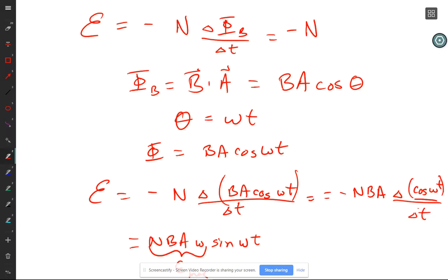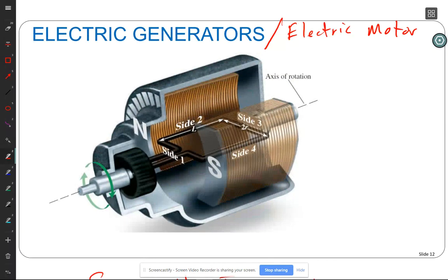And then those little coils are stationary. They're not flying about at high speeds. They're not going to be as prone to being torn apart by inertia, right? Because if things are going around in a circle, inertia makes them want to go straight. But since they're stationary, you don't have that. So it's more robust, it's going to last longer, and it's more efficiently producing electricity. So the difference in an alternator and generator is that a generator has a fixed magnet and a rotating coil. An alternator has fixed coils and a rotating magnet.